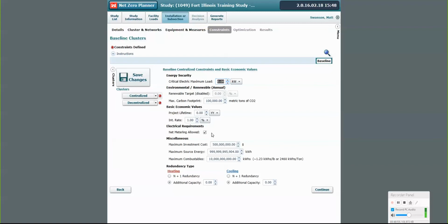So that one section that you're looking at updating could have some electricity production that exceeds, during sometimes, its own demand, and if you don't allow it to net meter, then you're going to have to basically just throw away any electrical production that's above its own demand. But if you allow net metering, which again saying that there's other parts of the installation that could use it, or you could net meter for the installation in general, then it's more cost effective.